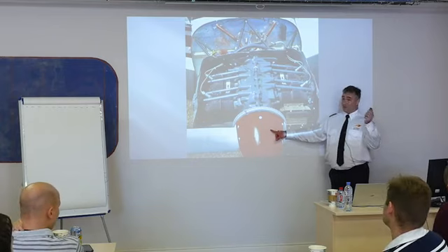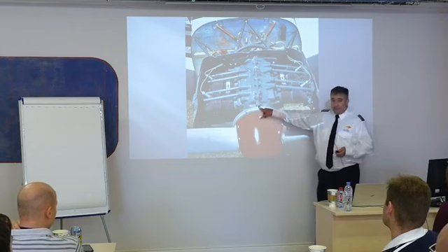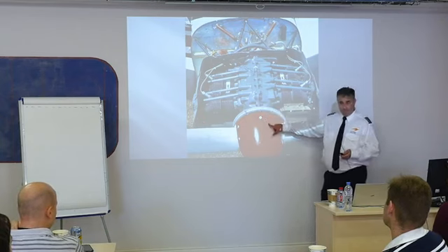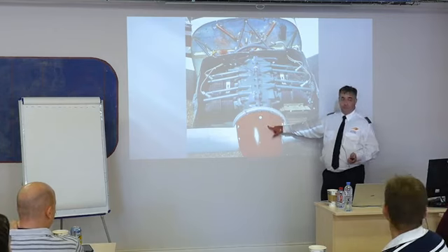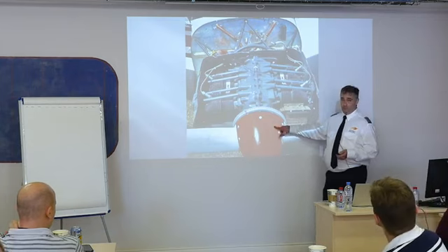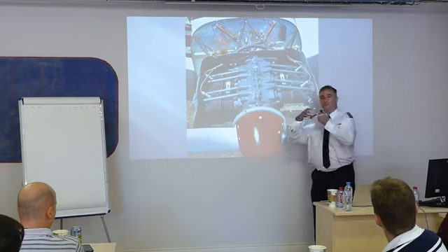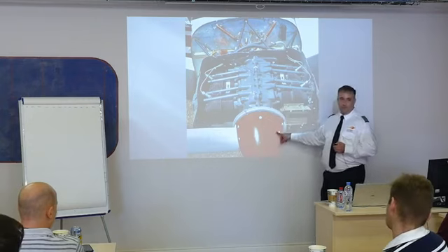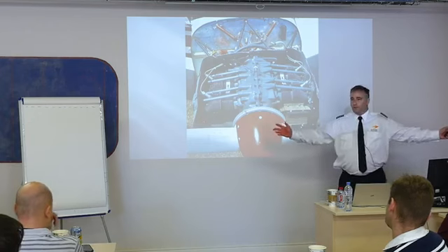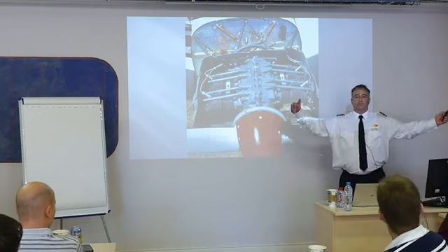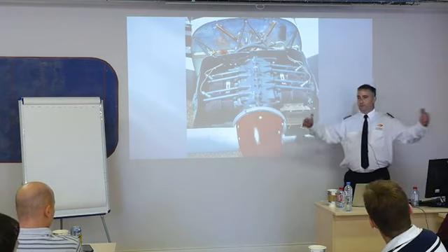Directly, and that is a great thing that you said, because it's bolted to that crank. Some airplanes, and we have one of these airplanes, have gear reduction. It means the engine spins at a higher RPM, but then that RPM is reduced to the propeller. These propellers are generally 75 inches, so a little more than 6 feet in diameter.